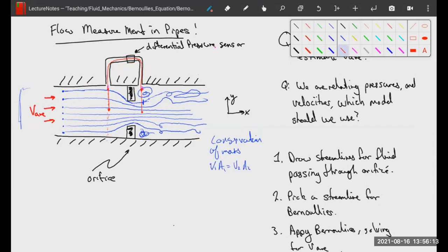Okay, the other thing which we will talk about in our problem for our quiz, not quiz, is that differential pressure sensors actually have a diaphragm inside of them that separates the fluids on either side. Now, there's not supposed to be fluid flow through this tube.